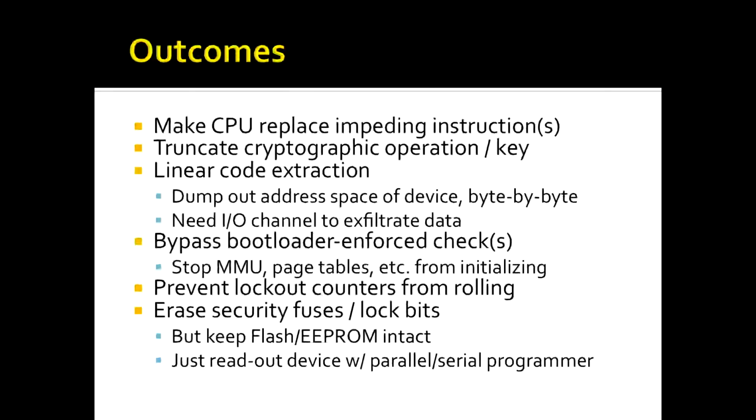You can do things like bypass bootloader enforced checks, so you can stop the memory management unit or page tables from initializing if they're mapping in sections of memory over top of the bootloader to hide it or conceal it or just to provide more space. You can stop that from happening. In some cases, you can prevent lockout counters from rolling. So if it's a secure crypto memory or something like that, where you only have so many tries before you're locked out of the device, if you glitch when it's recording or decrementing your try counter, the number of tries will never change. So you can just keep doing your malicious activity over and over again without the device finally reaching zero and then erasing itself or halting or something of that nature.